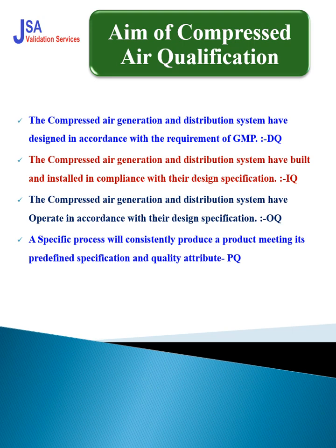And the compressed air generation system has to be operated in accordance with the design specification, functional specification, design functional specification, that is called the OQ. And a specific process that will consistently produce a product meeting its predetermined specification and quality attributes, that is PQ. It means what is our requirement specification for the compressed air generation system, that will be our PQ.